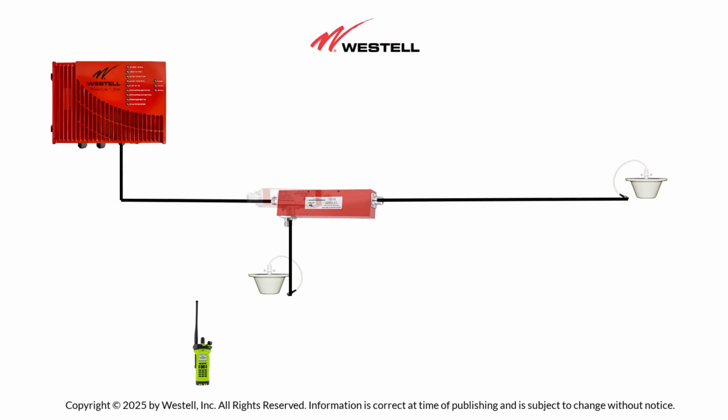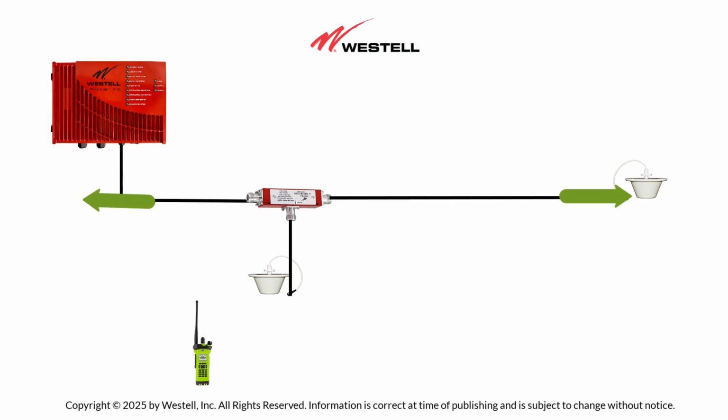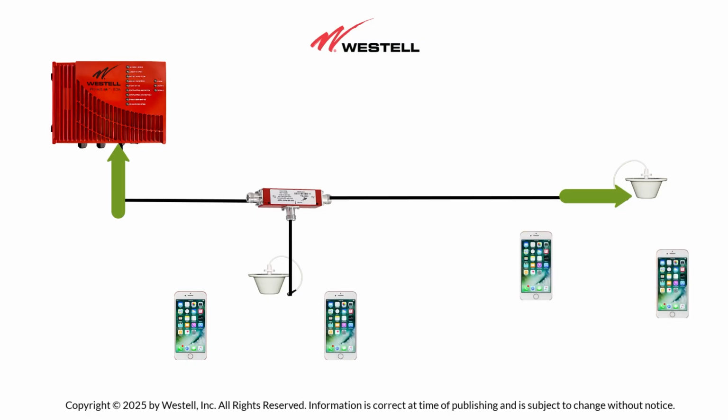However, if we replace the directional coupler with a tapper, the signal's power will be split equally towards both the BDA and other antennas. While this may not significantly impact first responder radios, it can pose performance issues for cellular systems. In modern cellular networks, such as 3G, 4G, and 5G, each handset interferes with all the other handsets.